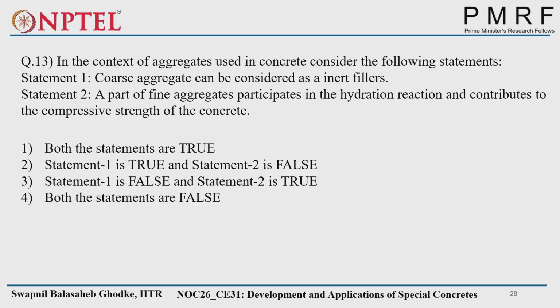So in the context of aggregates used in concrete, consider the following statements. One, coarse aggregate can be considered as inert fillers. Two, part of fine aggregates participate in the hydration reaction and contribute to the compressive strength of the concrete. Statement one is correct and two is false.